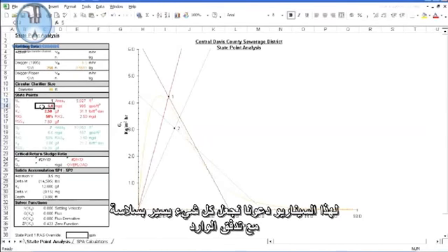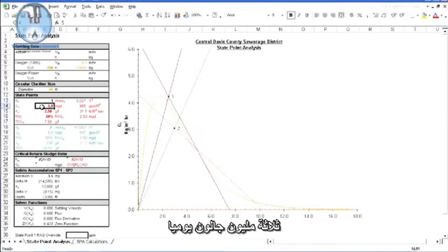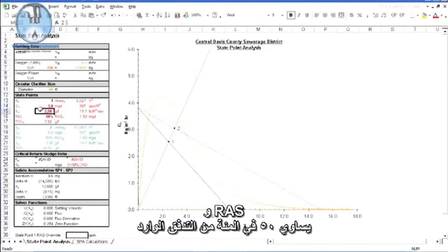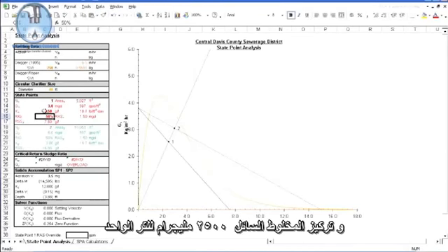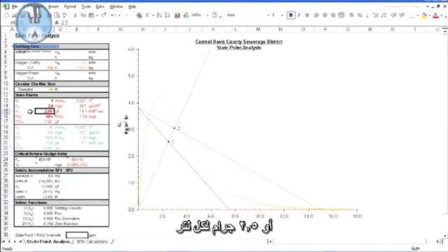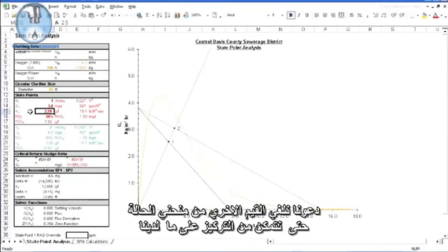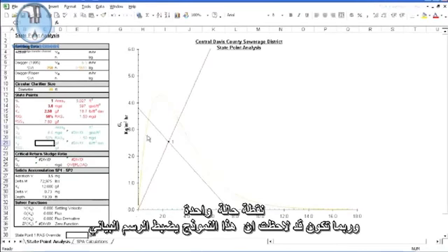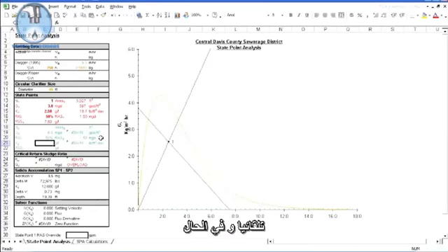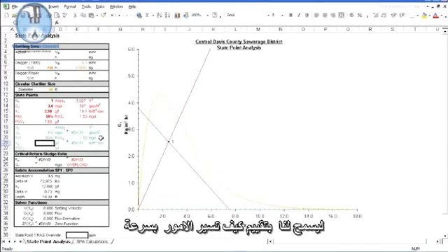For this scenario, let's have everything going smoothly with an influent flow of 3 mgd, a RAS of 50% of the influent flow, and a mixed liquor concentration of 2,500 milligrams per liter, or 2.5 grams per liter. Let's clear the second state point values now so we can focus on our single state point. And as you've probably noticed, this model adjusts the graph automatically and immediately, allowing us to quickly evaluate how things are going.